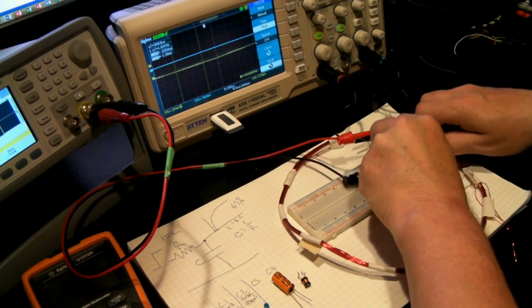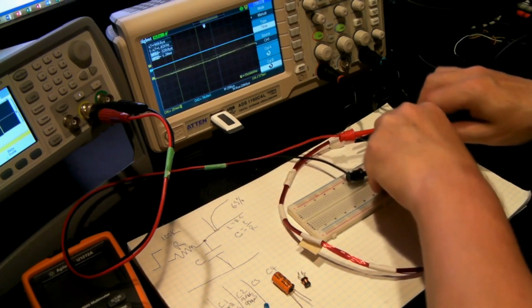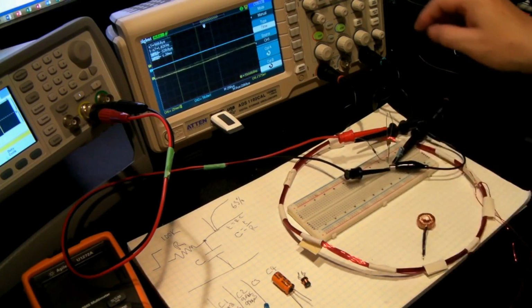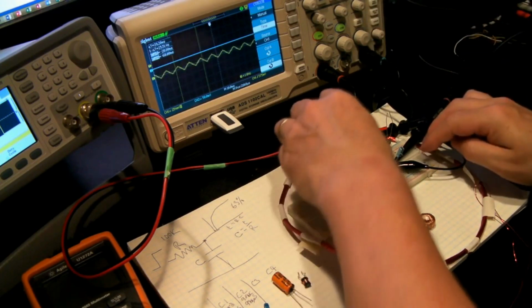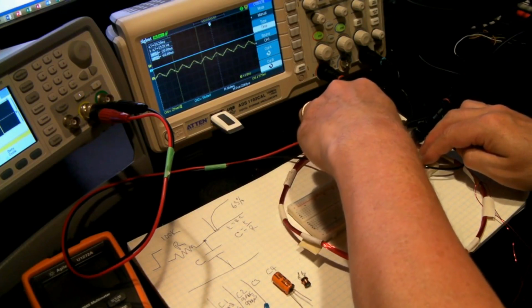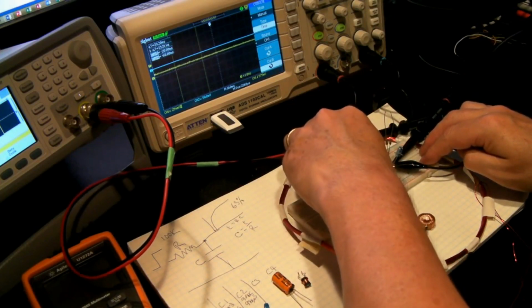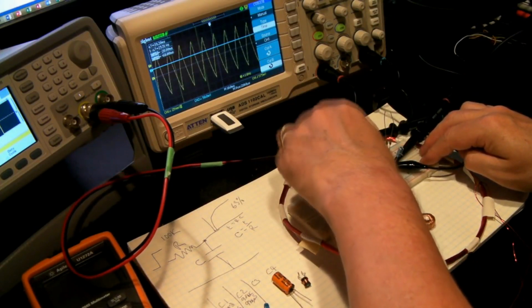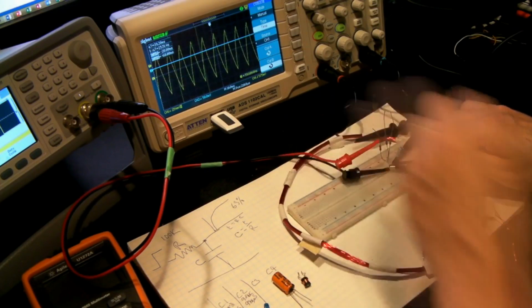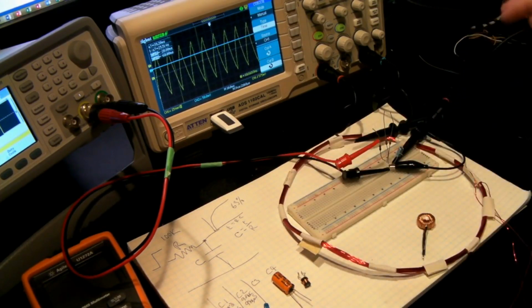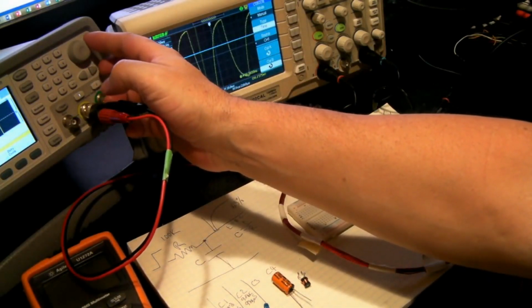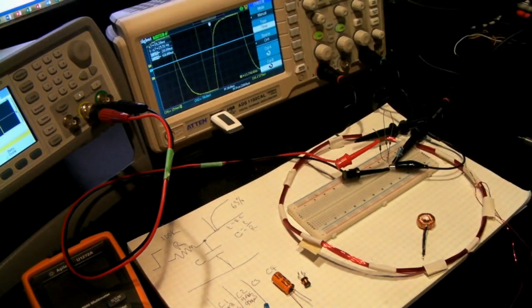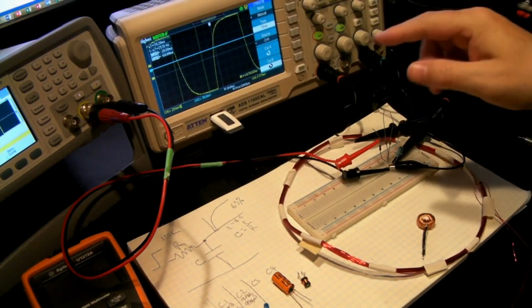Now this one we're probably going to find, because it's electrolytic, it's going to be a much higher value. It's going to be giving us a much slower signal. As you can see here, it's not even registering. So what I'm going to do is switch to the 1K resistor here, just to increase the resolution, or at least so I don't have to reduce the time base to some crazy value. So the frequency is still a bit too much, so I'm going to reduce this down to maybe 10 hertz. Yeah, that's sufficient there. So now we've got a 10 hertz square wave.